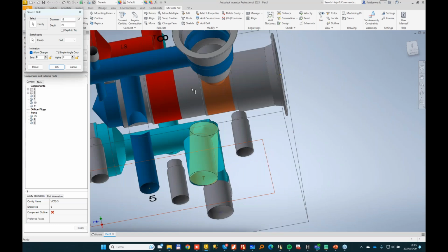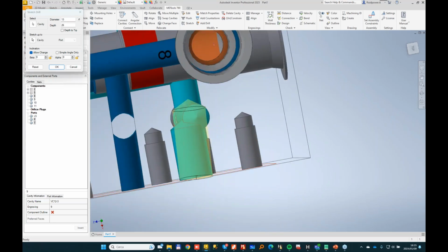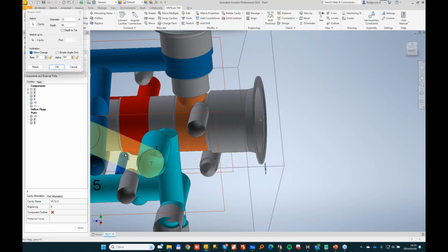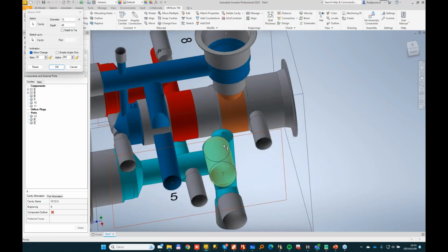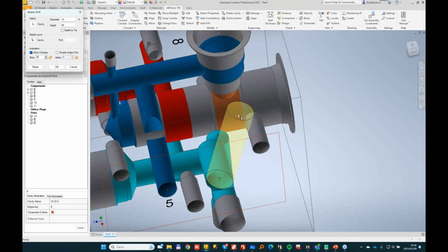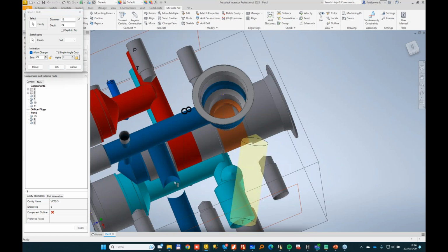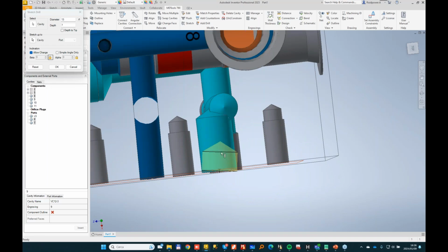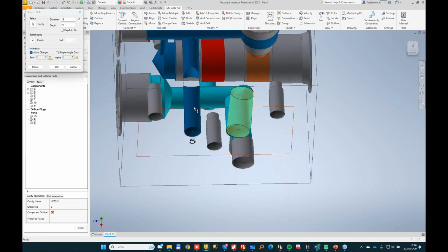When you drag the tip, pay attention, because if you don't lock the rotation, then you will be able to really, with freedom, rotate the drill. It is really out of control. So it's better to say 0, fix it, and then you will be able to stretch the drill, just changing the beta angle. But it's much easier to just type an angle, fix also that, and then you will be able to stretch only the depth. This is a common technique.